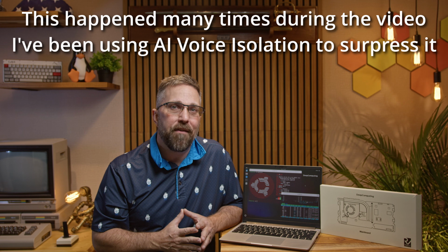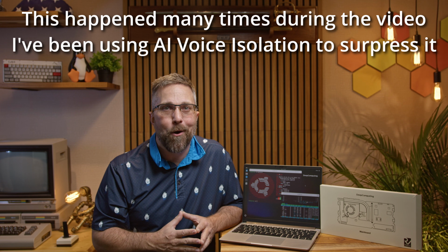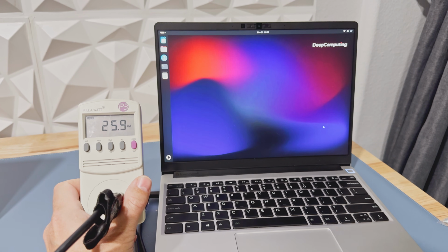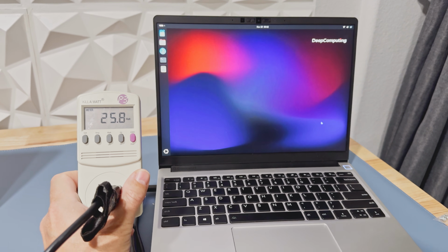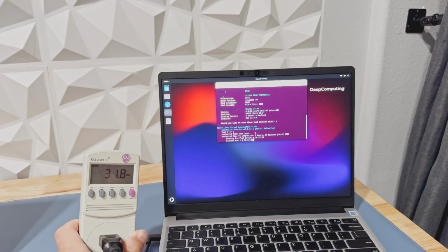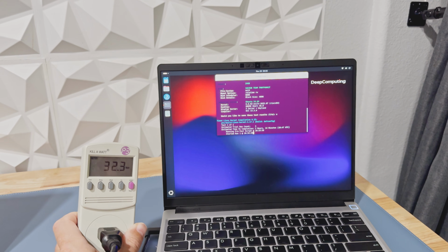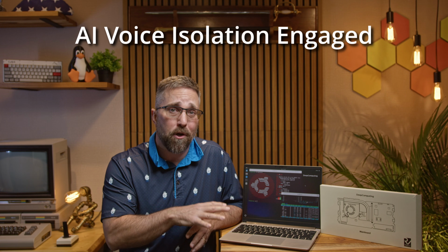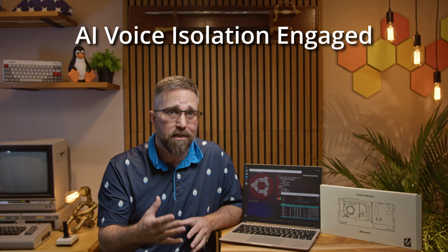As far as power efficiency, this i5 RISC-V SoC still has a long way to go compared to its ARM64 or even x86 counterparts. At idle, the system draws about 25 watts, and under full CPU load, it only climbs to around 31 watts. That's a surprisingly small delta under stress, which suggests the baseline power draw from the SoC, memory, and supporting components is already high, and that power management features like clock gating or deep sleep states aren't fully utilized.